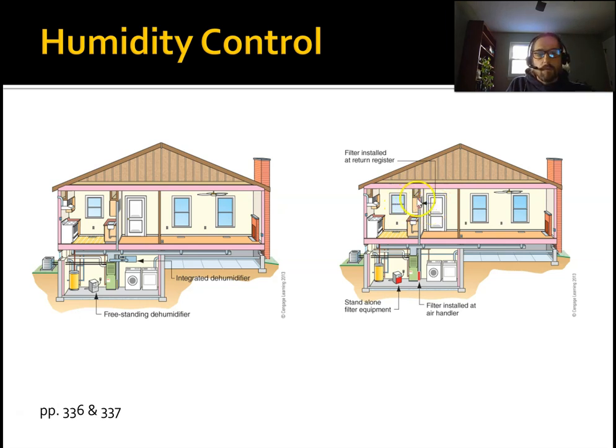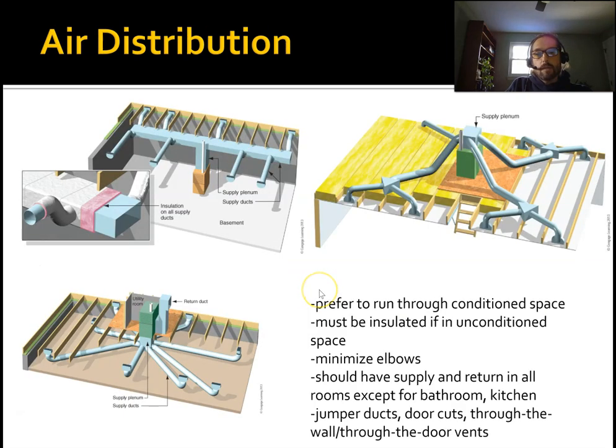This is really pretty uncommon to have in the rooms, but air filtration is really important. It keeps dust off the heat exchanger. It keeps dust off of the evaporator, which helps that operate better. It keeps dust out of the airstream, so it pulls out some of the particulates, pulls out some of the allergens and that sort of thing. So that is an important part of it.